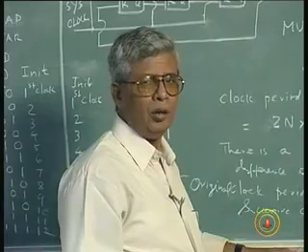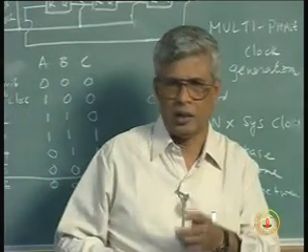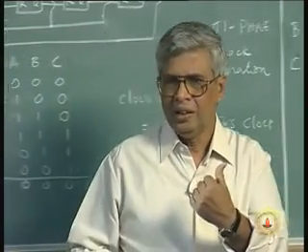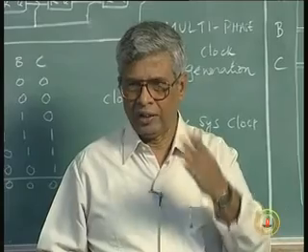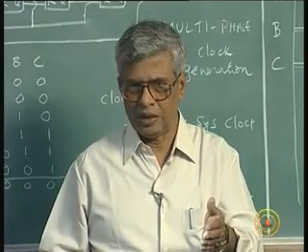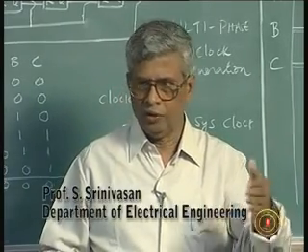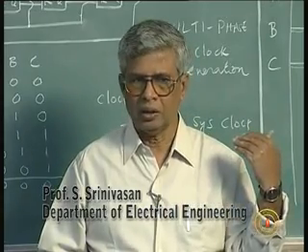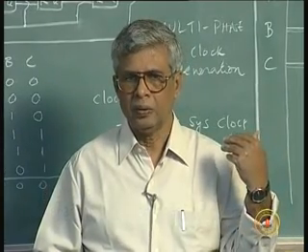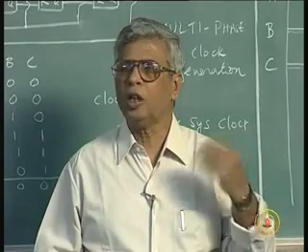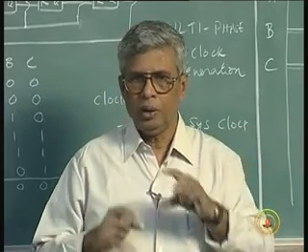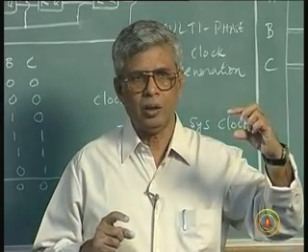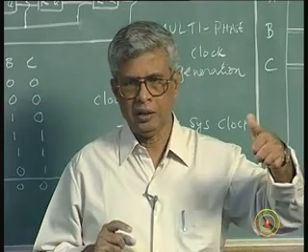This is also called a counter. See, in a counter, you give a clock pulse, and every flip-flop divides that clock by a factor of 2. Frequency is divided by 2 in every flip-flop stage. So similar thing here. So this is also a counter, but the only thing is, the output of this counter we twist and then connect it.